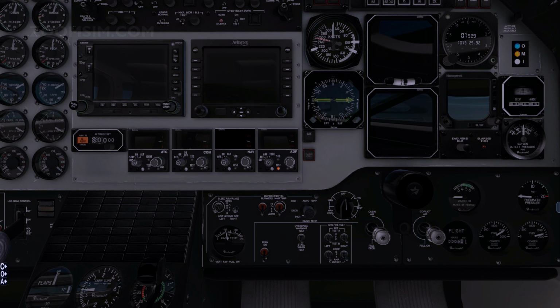To provide the maximum cooling rate, select manual cool on the environment mode control. Continued operation in this position is not recommended, as it may cause ice formation in the air cycle machine. There are 4 additional manual controls: the pilot's air, defroster air, cabin air, and the co-pilot's air. The controls provide the maximum airflow in the fully out position and minimum airflow in the fully in position.